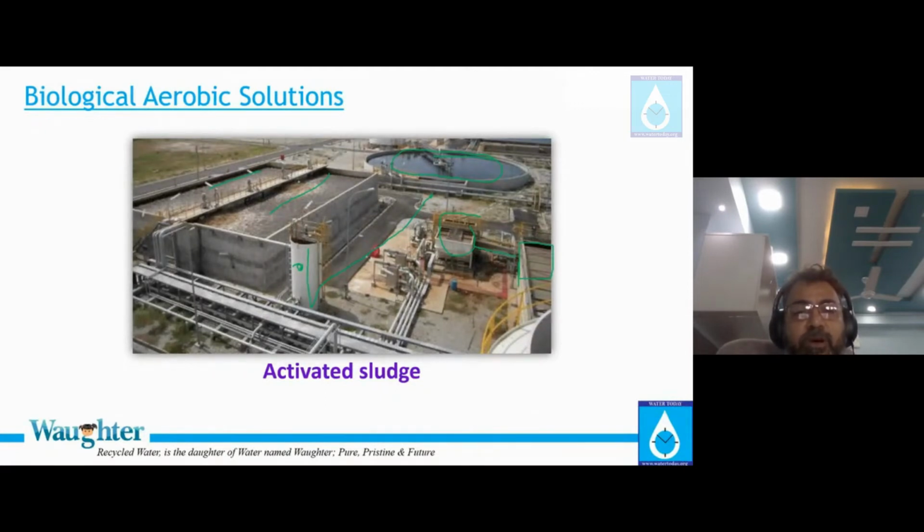What you see here on top are surface aerators. One surface aerator, two surface aerators are right now working. This one and this one are not working. Probably the surface aerators are linked to the DO of the water. So if adequate DO is there or not, the third aerator will work for some time, then after that they'll stop and something like this will work out. It's a huge wastewater treatment plant.